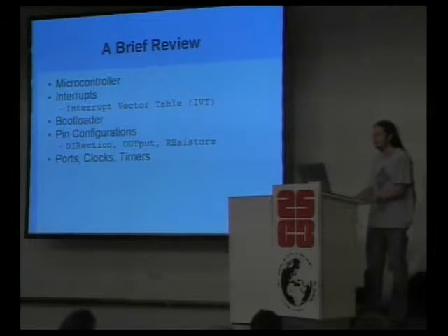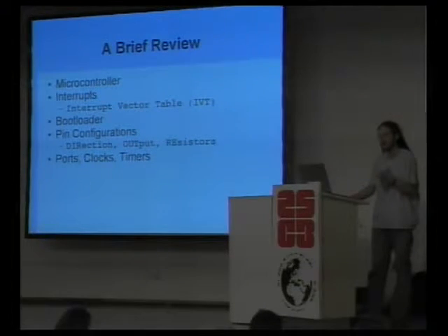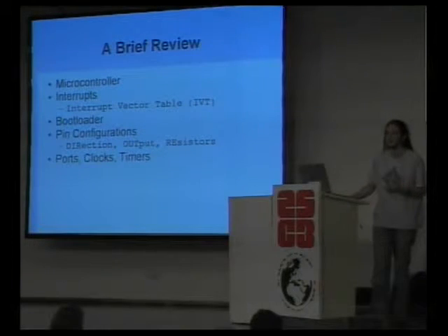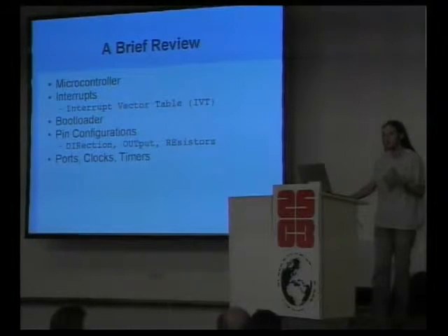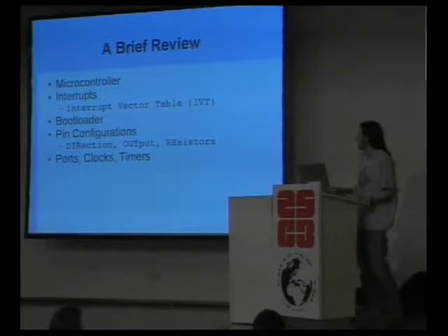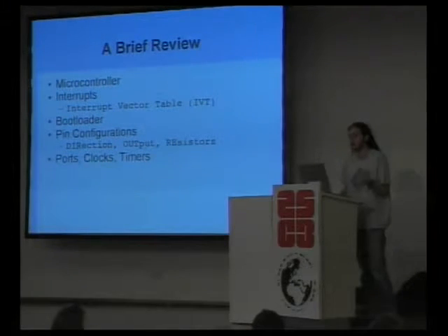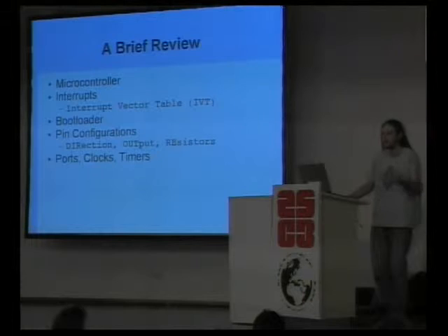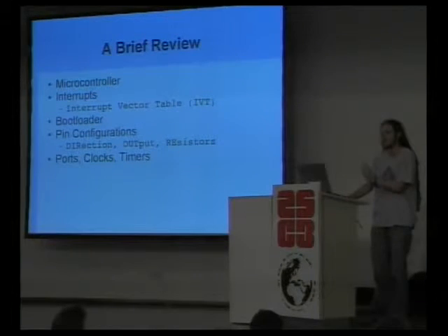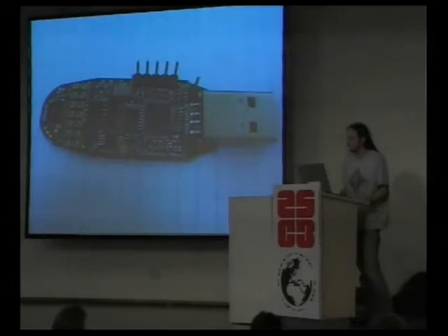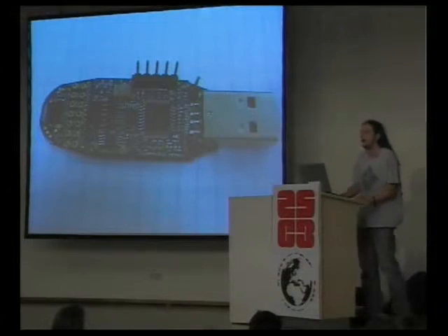Also, a microcontroller doesn't have a real operating system in it. So instead, you have individual memory mapped addresses that you write to affect the outside world. So you can change pull up and pull down resistors on an I/O pin. You can change that pin from an input to an output. You can pull it high, pull it low. And there are also clocks and timers and such that you can access by peeking and poking individual addresses. And when you do this, you're not calling a function that exists elsewhere within the chip. You're just writing to an address, waiting a bit, and then reading from another address, or waiting for an interrupt to fire.